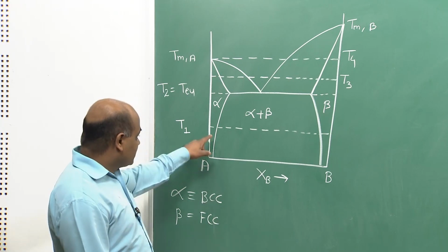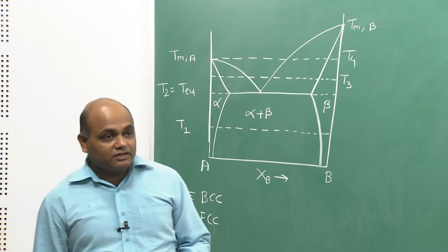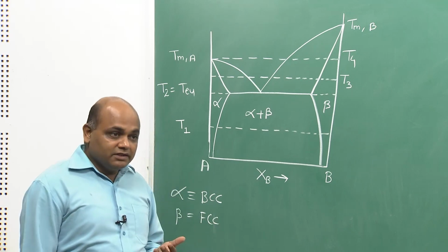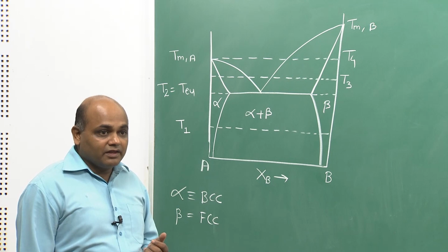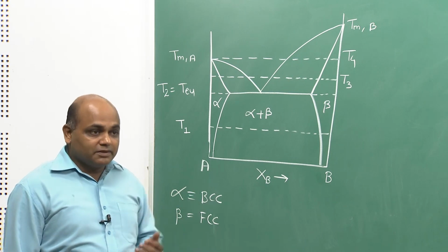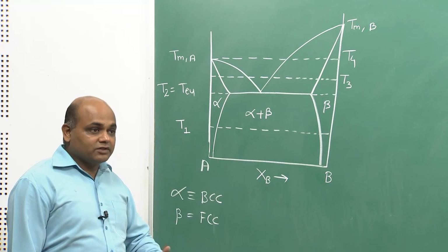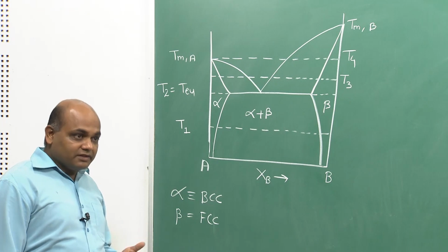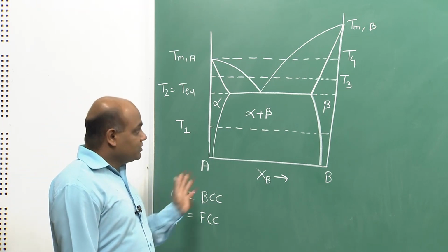So, how do we get to this from the Gibbs free energy versus composition phase diagram? In computational thermodynamics, essentially we evaluate the Gibbs free energy curves for different phases, and then from this Gibbs free energy versus composition data we derive the phase diagram. That is the actual way we go in computational thermodynamics, but to understand the process really well, let us do it a reverse way,